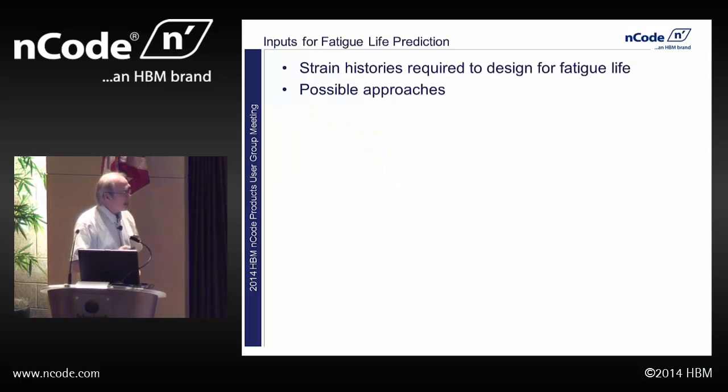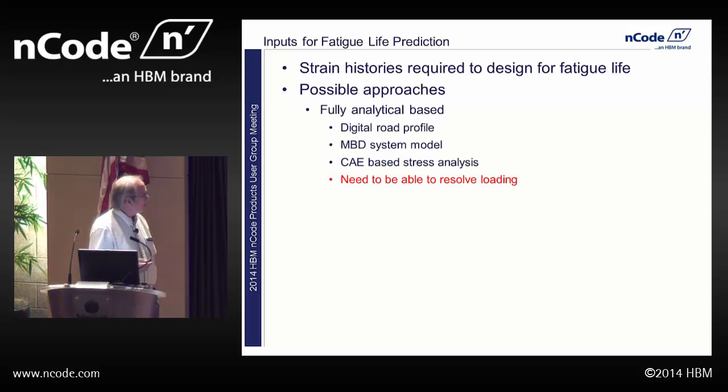Okay, and again, just stepping back and thinking about fatigue, we need to be able to produce strain histories or stress histories to do fatigue on. And if we're looking at something like DesignLife, what we're doing is we're using FE stresses and measured loads of some sort, putting them together to create these strain histories, but we need those histories one way or another. And so there's ways that we can go in and create these.